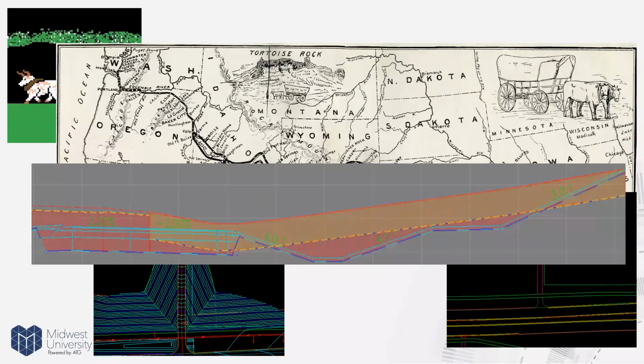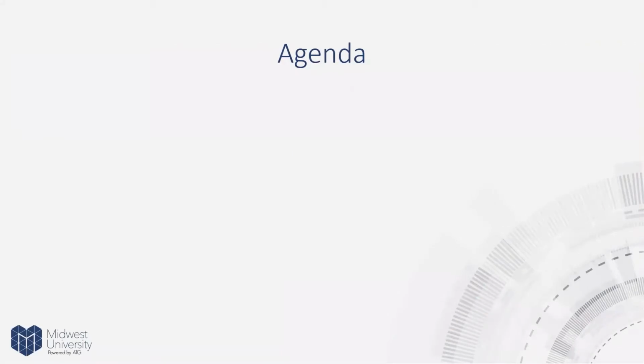What we're going to go through in this particular class is going to be subassembly review. We're going to go over some of the out-of-the-box stuff, and then how you can create some custom subassemblies, and not just using SubAssembly Composer. I'm not going to make this a SubAssembly Composer class. That could be its own class, but I'm just going to touch on a few ideas, and also how you can make some custom subassemblies right inside Civil 3D for use in your corridors.